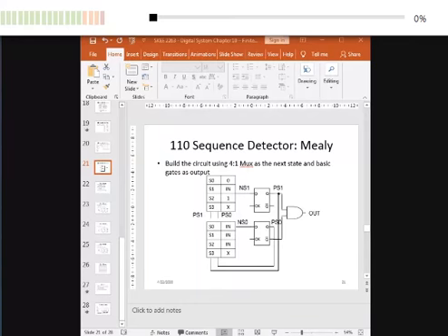So, but if you have only 7 segment, you can still show 8 bit result. How? Anybody can give idea? Show everything in hexadecimal, the result. Input you can show in binary, it is easier for you to see what's going on if you show the input in binary, but you can convert into hexadecimal at the output.